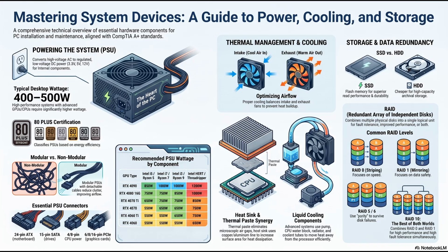The physical environment inside the loop is harsh. The continuous temperature swings break down the anti-corrosive chemicals in the coolant. Furthermore, if you accidentally mix metals in your loop, say a copper water block with an aluminum radiator, the liquid acts as an electrolyte, triggering galvanic corrosion that will literally eat away the metal blocks from the inside out.